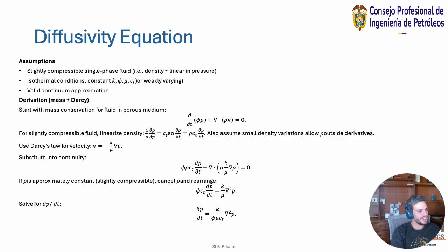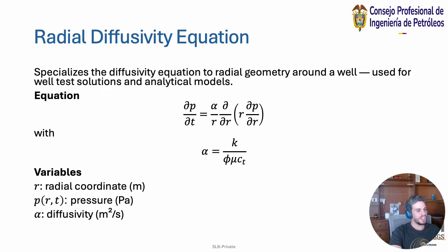And one thing to note is that we can have this diffusivity value or parameter now that we can write in terms of permeability, viscosity, porosity, and compressibility, right? And this governs the real pressure gradients for things like reservoir simulation, numerical reservoir simulations, or something called Green's function. So it is extremely important, and this is where we're entering the real world of the mathematical applications into our simulations, or into our modeling.